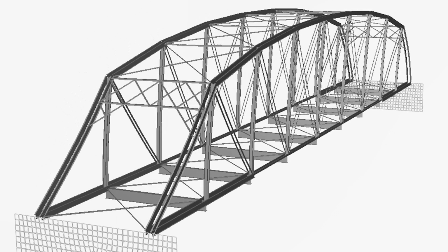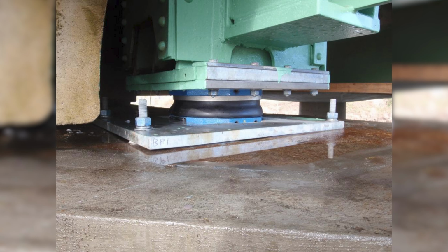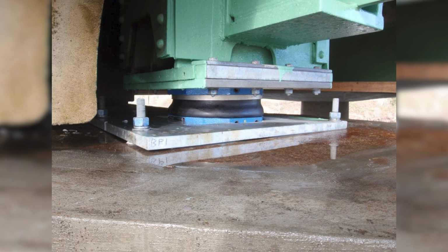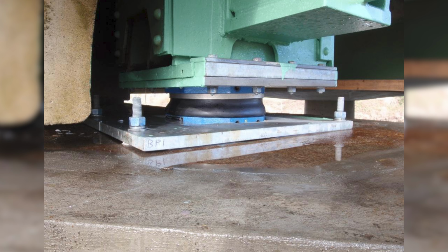So typically a bridge superstructure interfaces with a substructure through a thing called a bearing, actually through a series of bearings, typically one under each girder line. Those bearings, in some cases there are some sophisticated types of bearings called isolation bearings, which are actually designed to help the structure withstand the earthquake with lower forces by altering its dynamic response.